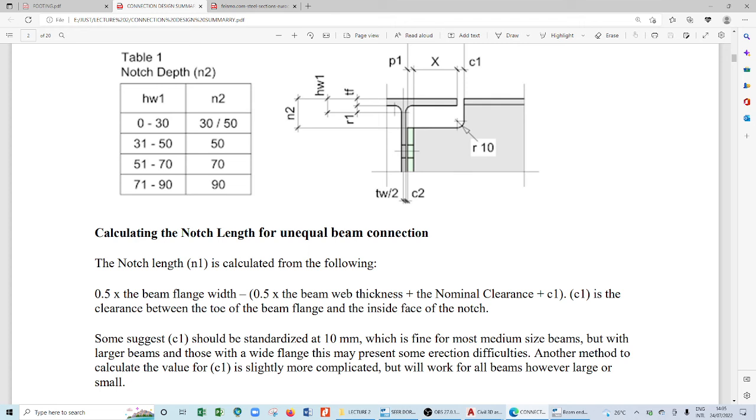This one is dotted. Because they are equal, if you bring this one to touch this, it will just stop here. So you must recess it so that this comes and touches here, so that you can weld. That's what we are trying to do.